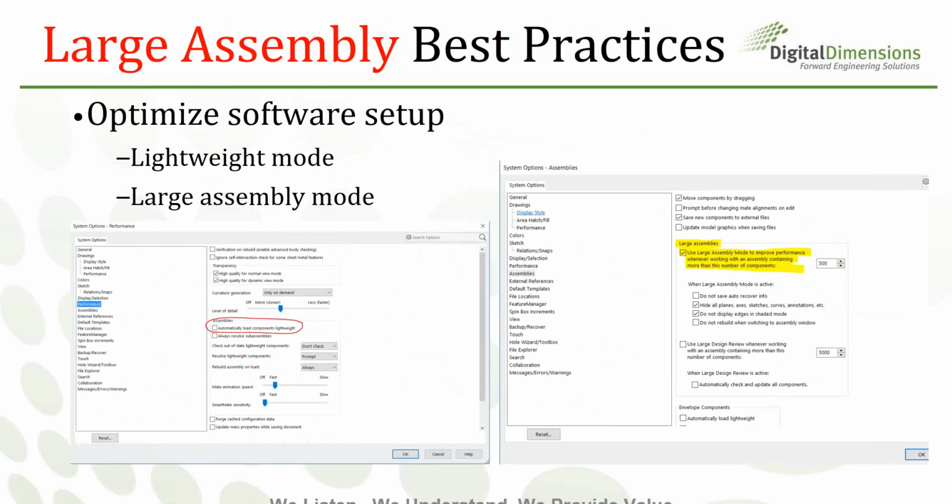So when you need the part features, simply right click and then set the part to resolve or edit the part, and that step will load the individual parts into your RAM.